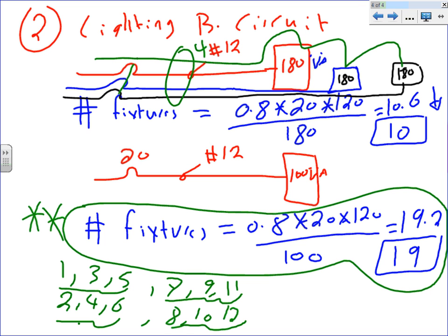Yes. If you want to wire with MC cable, bring your home run the cheapest way, bring your home run conduit to the first box, take your MC cable and go from fixture 1 to fixture 2, to fixture 3, to fixture 4. You don't have a limit of how many you can feed because you're feeding fixtures. But at the end, you can't feed a receptacle from the same circuit. Remember that rule. You can feed a light, a switch, from a J box here, whips to here and here, all on the same circuit or different circuits.